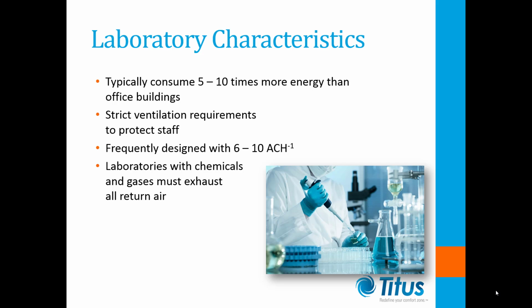Depending on the lab use and classification, the HVAC systems will frequently be designed to deliver 6 to 10 air changes per hour, and additionally, labs where gases and chemicals are present must exhaust all return air.